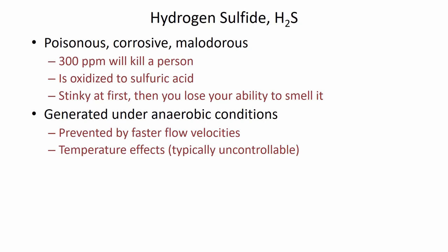When you have anaerobic conditions, meaning that the water flowing through the pipe runs out of oxygen, then bacteria will start to break down sulfur and form hydrogen sulfide.